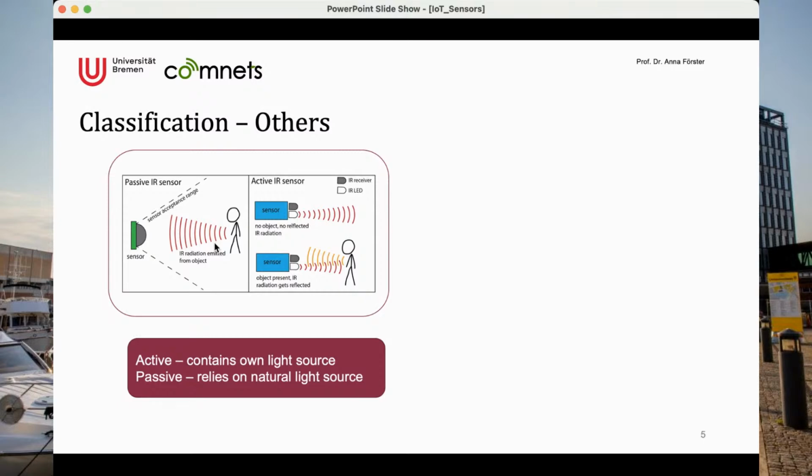Some people have a small misunderstanding here when they use sensors in software implementations, that they expect the sensor to return a value immediately. So they expect to have some sort of a function call, like temperature sensor get value, something like that. And that works well if it is a passive sensor, which can really read it straight away and return the value immediately. But that doesn't work if you have an active one.